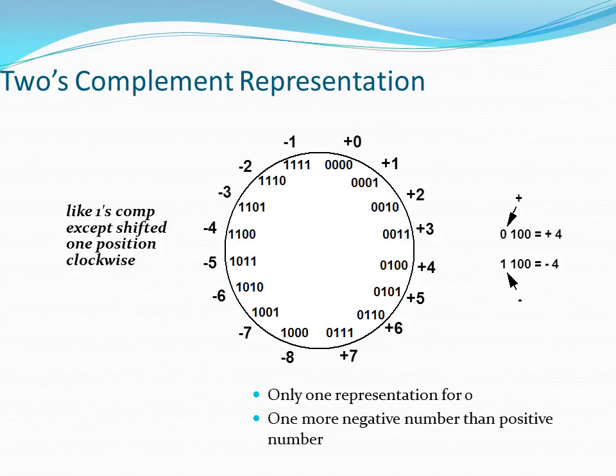Observe that sign magnitude, signed ones complement and signed two's complement are the same for positive numbers; the difference is only for negative numbers. In this case, we represent a negative number in signed two's complement by taking the complement of the positive number and adding 1 to the complemented number. So we can get the 2's complement of a negative number.